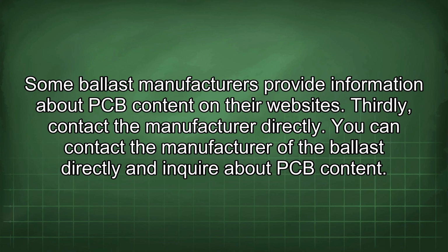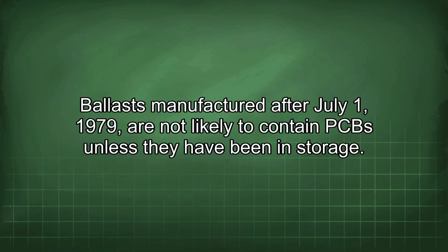Thirdly, contact the manufacturer directly. You can contact the manufacturer of the ballast directly and inquire about PCB content. Ballasts manufactured after July 1, 1979 are not likely to contain PCB unless they have been in storage.